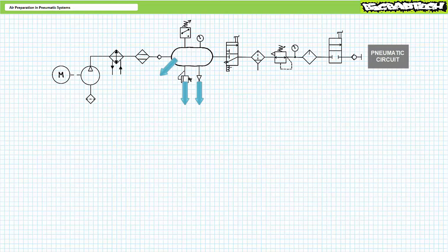Given the receiver is a source of pneumatic energy with leaks in it, most likely the compressor will experience excess runtime because a leak would continually bleed off pressure inside the receiver. As such, pressure in the receiver only briefly or may never rise to the pressure switch's set point, and the motor remains energized and the compressor keeps running and running, all the while the tank keeps leaking and leaking.